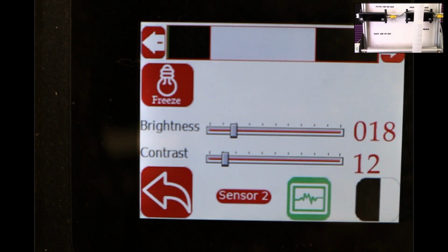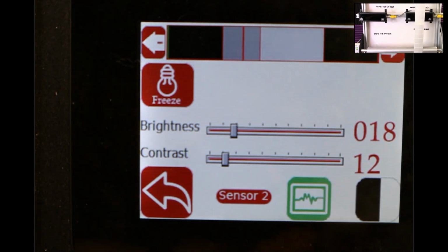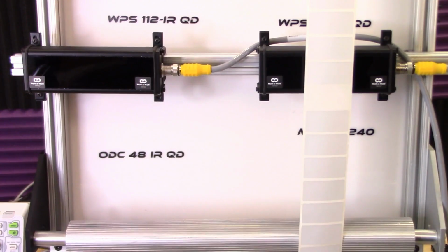Anytime we do width measurement, we need to make sure that the plane of the web is stable. The best way to do that is to install the sensor between two fixed rollers. That's what we have in the setup here, and that way we can take care of that. That's the first thing for the width measurement application: we don't want to measure the width of the web at the exit of the web guide, because at the exit of a web guide, the corrective action of the web guide is going to change the plane of the web, and we can measure the width, but that's not going to be accurate to 5/1000ths of an inch like what our sensor can do. That's the first and foremost thing that we want to do.